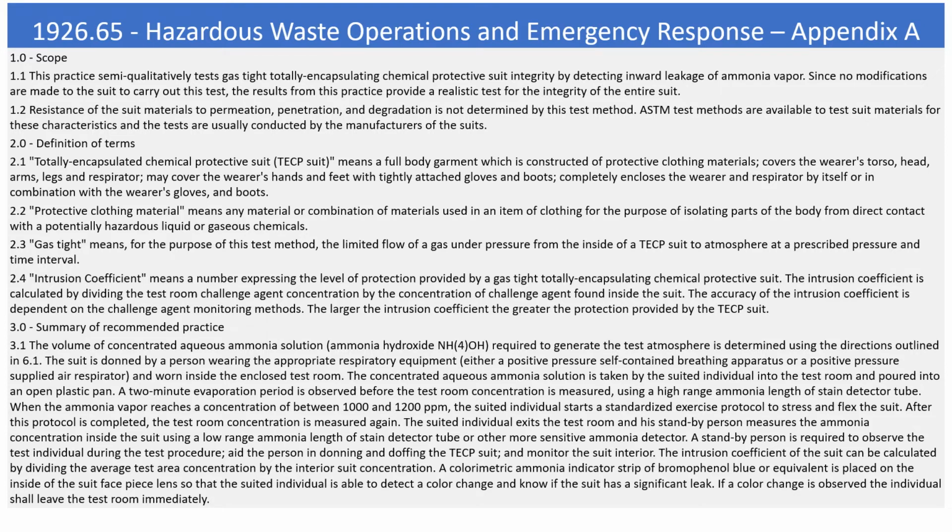The suited individual exits the test room and the standby person measures the ammonia concentration inside the suit using a low-range ammonia length of stain detector tube or other more sensitive ammonia detector. A standby person is required to observe the test individual during the test procedure, aid the person in donning and doffing the TECP suit, and monitor the suit interior. The intrusion coefficient of the suit can be calculated by dividing the average test area concentration by the interior suit